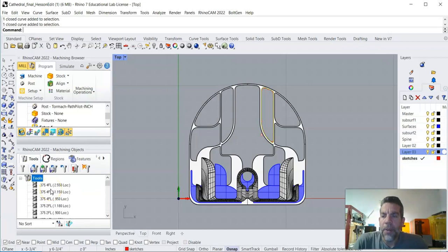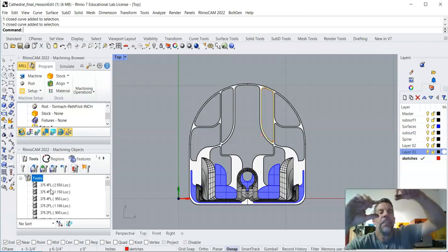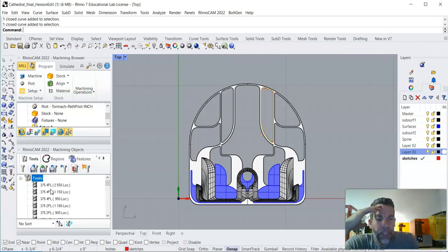I don't get too hung up on putting in exact dimensions of tools unless I'm worried about how deep I'm cutting. The main factor that's important is obviously the diameter of the bits. That needs to be right. That needs to be correct. But length of cut only really matters if you're cutting thick stuff and you've checked against your end mill, and you can tell that you're going to wind up having a collision because it's got a larger shank than it does cutting diameter.